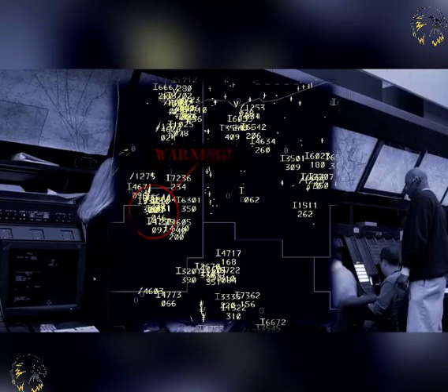Radar systems should not only display the position of an aircraft spatially, but also provide for the display of safety-related alerts and warnings, including confliction alert and prediction, minimum safe altitude warnings, and unintentionally duplicated secondary surveillance radar codes.